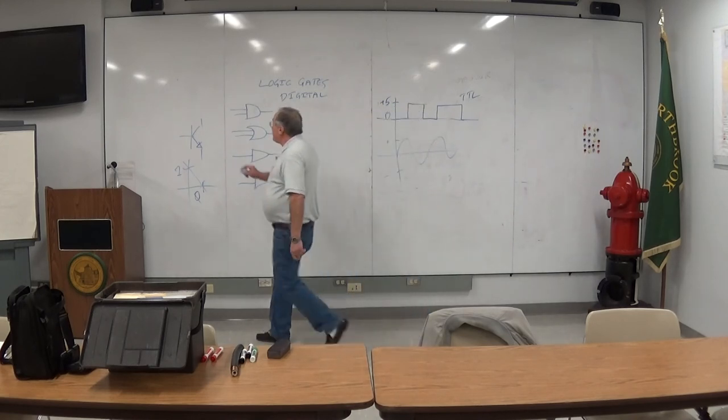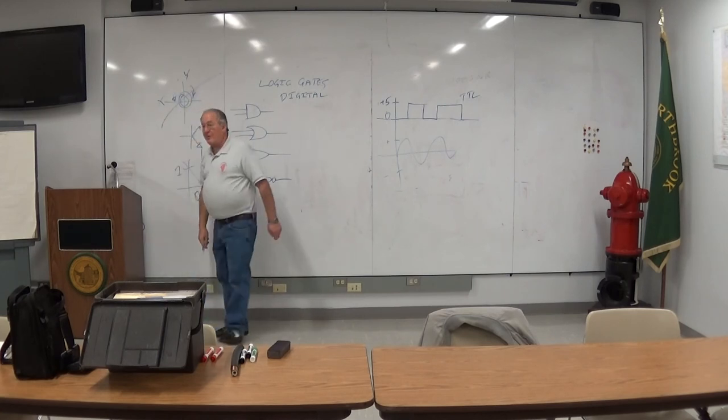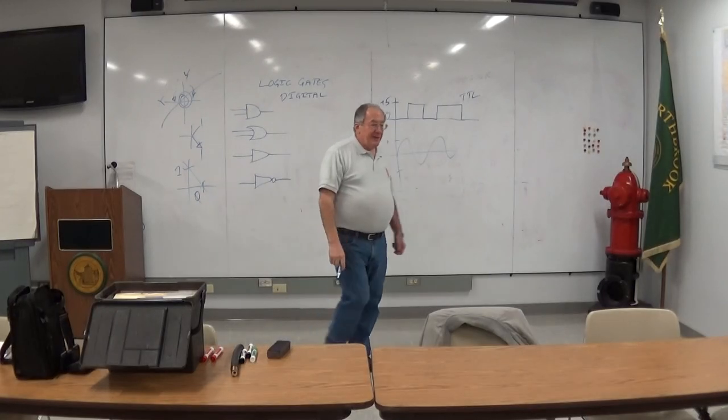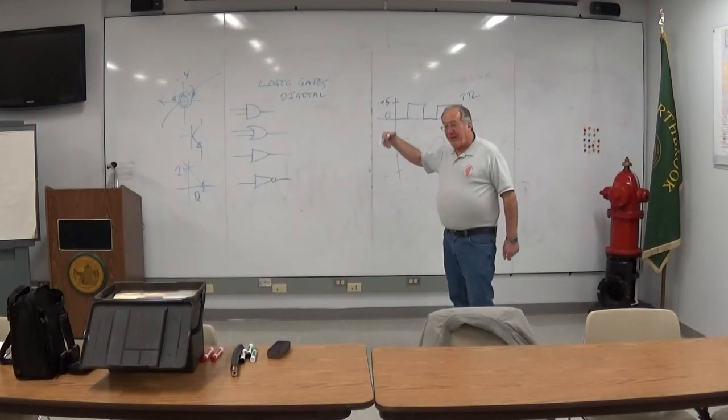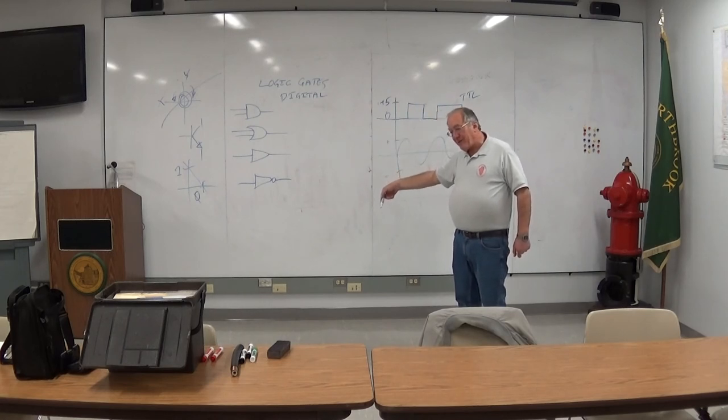In the days when we used to store information in a magnetic donut, there were two wires called X and Y, which when there was enough current going through, would actually cause the magnetization to change from going clockwise to maybe going counterclockwise. And the sense line that went through it would determine which way that was. It would have to do it destructively, by the way. It would have to actually reprogram that donut and get a different voltage blip if it was already programmed the way you were trying to program it, versus if it was programmed in the opposite sense.